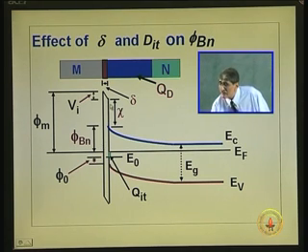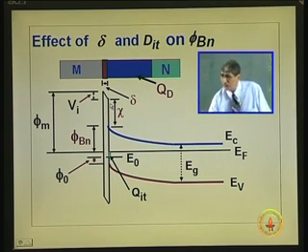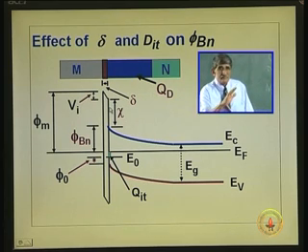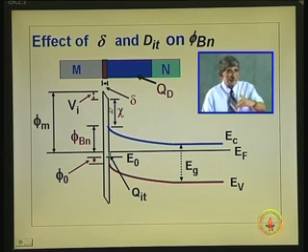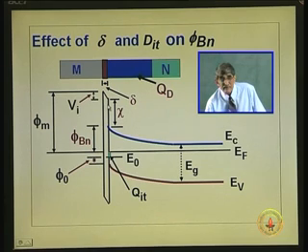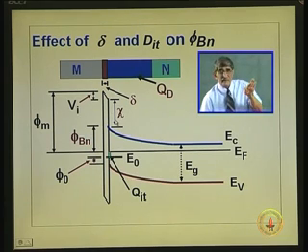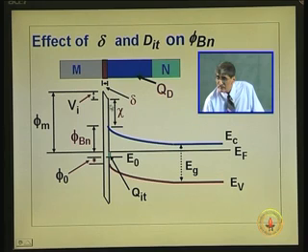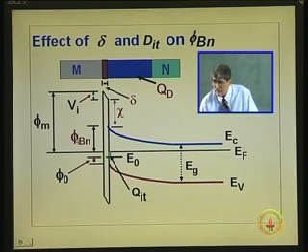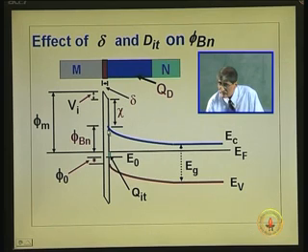So, the field is in that direction from right to left. So, the conduction band will be sloping up like that. Whenever plus is up, the energy band diagram will tip down. So, that is there, a constant electric field, so the slope is linear for that. So, that is the 0 level. From here to here you have got phi m. I am just going slow because you should identify each one of those terms. And when the band bending is there, if this layer is very thin, there can be tunneling. So, the actual barrier height is this point, that is the phi b n.